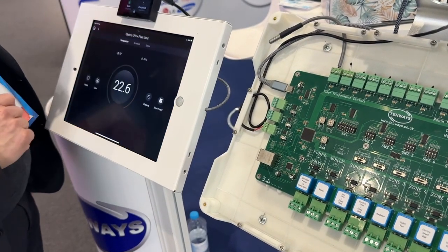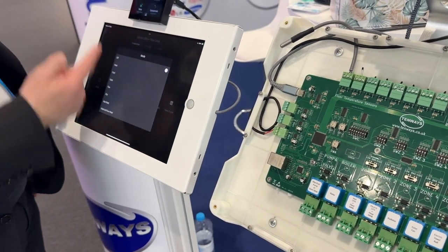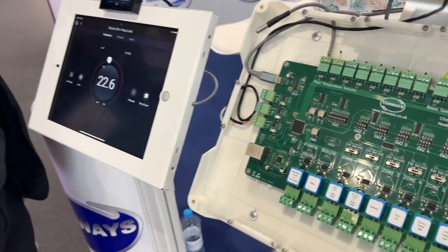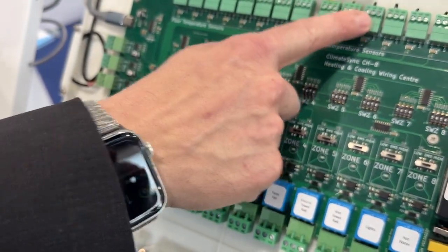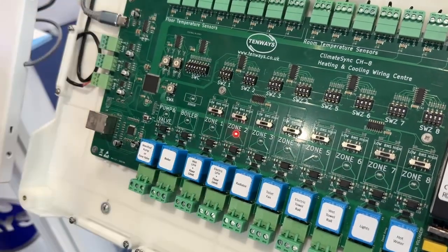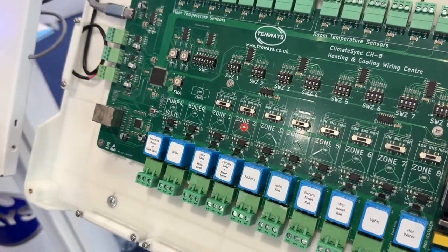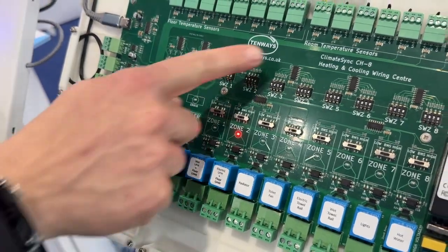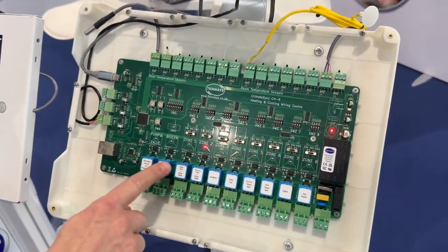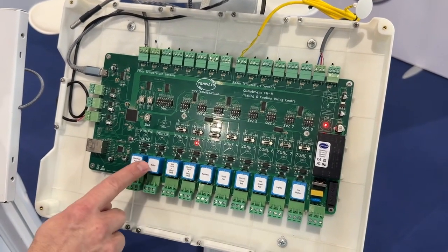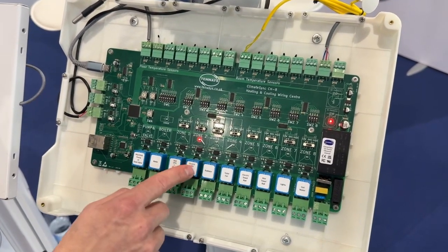We will go to the next room with electric underfloor heating. We will switch it on now, and the zone went on, temperature dependent, with both room temperature and floor temperature limit. So we can have two sensors, and this is an NTC sensor, any resistance. Default is 10K, but you can use any resistance. You just have to set it up. But as it is electric underfloor heating, it did not activate the boiler and the pump, as that is a zone.